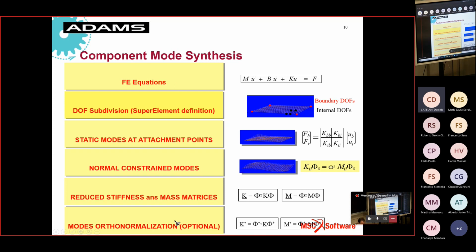This sequence of analysis procedures is automatically performed in the finite element code, by clicking a specific analysis. In Nastran, for example, this analysis is Sol 103, typical modal analysis. So when you want to have a flexible body in Adams, it is very easy.